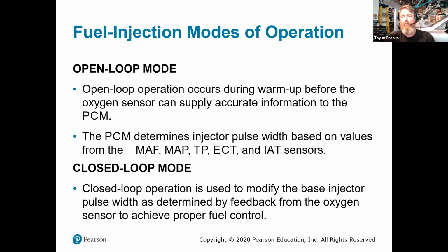Engines tend to have less hydrocarbon emissions if they run on the hotter scale of the combustion process, and therefore you're less likely to produce that harmful emission gas. So we'll start to see operating temperatures on more modern vehicles be a little bit higher, sub 220 operating temperatures, but very much within that 200 to 210, 215 operating range, which does give me a little bit of anxiety as a mechanic because you're right on the verge of causing massive overheating.